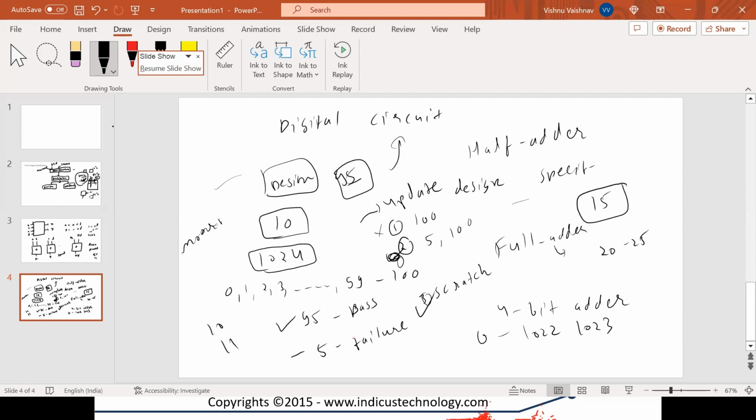Now, what will the designer do? He'll just add something and get the design ready. But what about the verification engineer? The combinations are increased from 1024 to 2048, double. Every single input you add in the design doubles it.